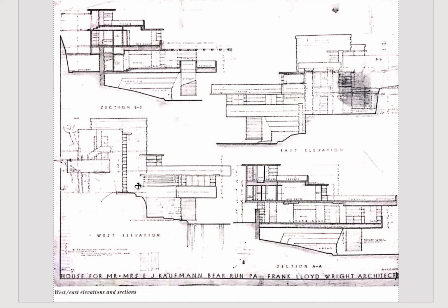And in this case, looking at this drawing, say I had 3 pencils. The darkest would be the things that are cut through. The second would then be the outline and the openings. And then the third would be the details. I guess there would be a fourth here. He's got 4, because then there's the dimensions that are the fourth.